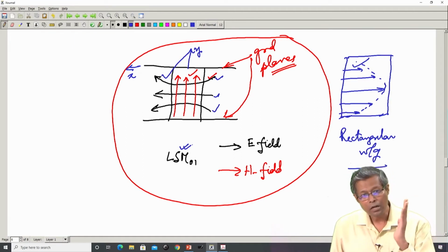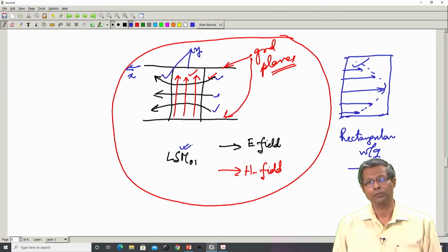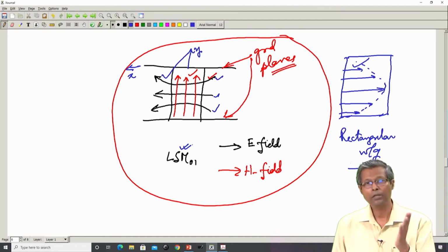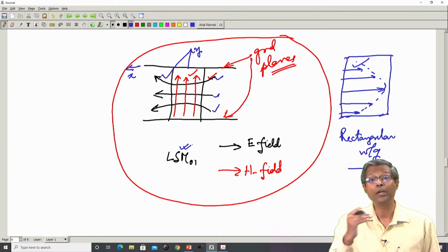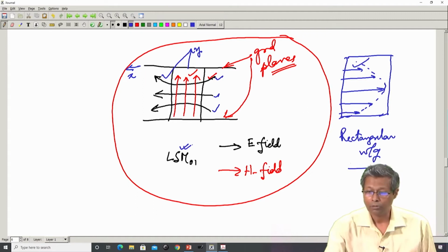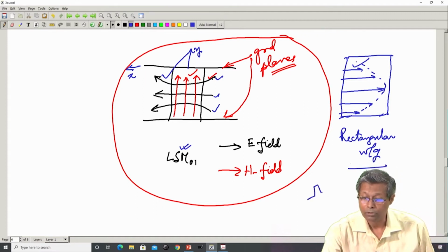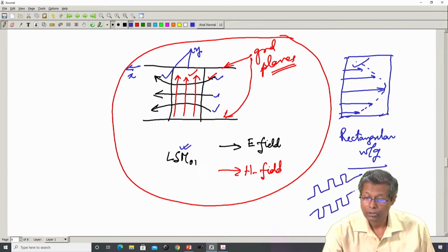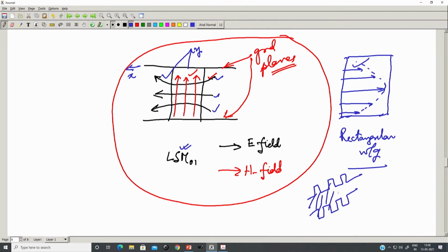So, if I insert a metallic plate, or typically it happens like a corrugated plate kind of thing with a structure like this, a corrugated type plate. Okay. So, this is an example or a typical picture of a mode suppressor, and this will be inserted where this is the y and that is the z direction.